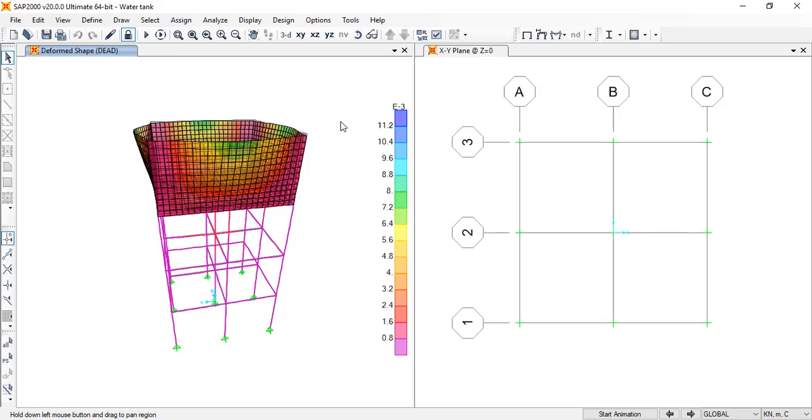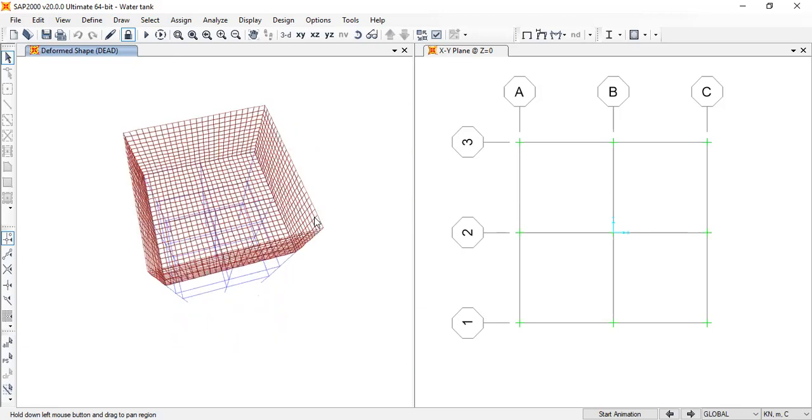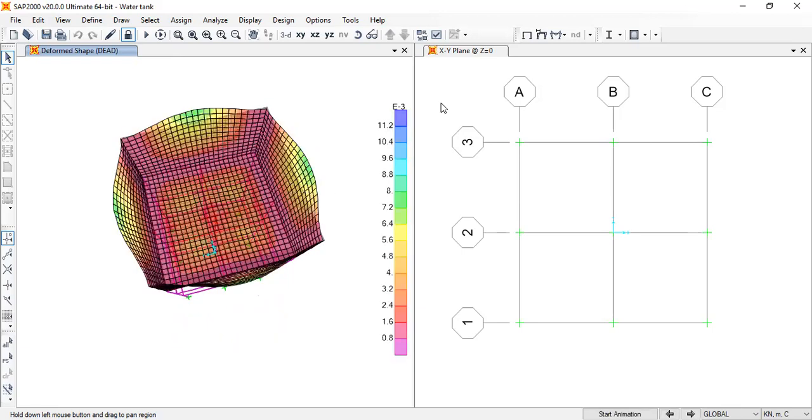So that joint pattern is a fairly simple thing, but it is a concept that we idealize the water pressure, right? It is how we idealize the water pressure on each wall. And on the bottom wall, you know that the surface pressure is uniform, so apply it as a uniform pressure, right?